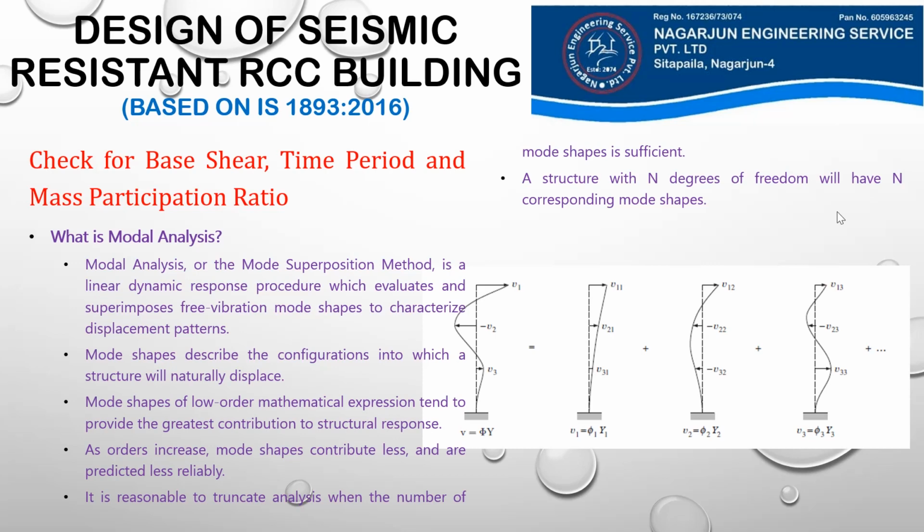So what is modal analysis? Modal analysis, or the mode superposition method, is a linear dynamic response procedure. Since the other name is the mode superposition method, this superposition principle is valid only for linear structures. Modal analysis evaluates and superimposes free vibration mode shapes to characterize displacement patterns. So what is free vibration and what are mode shapes?